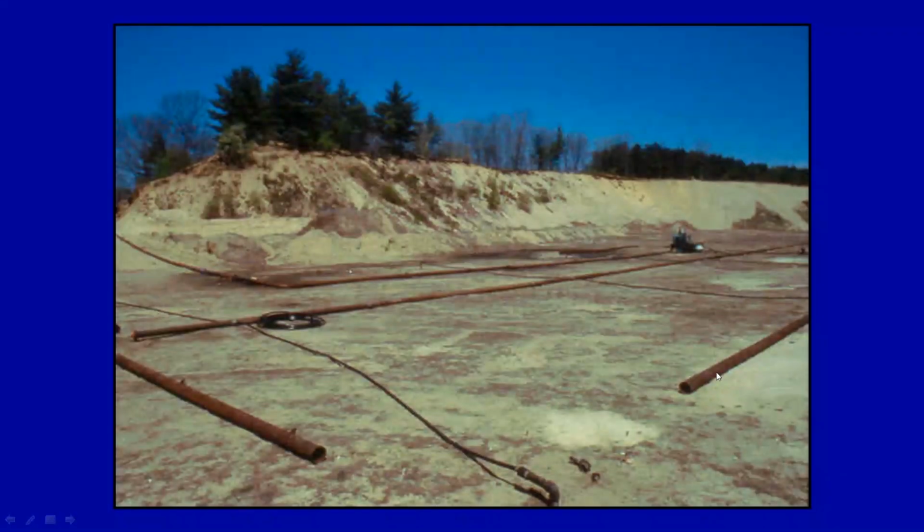Here we have an example of a shallow aquifer. This is going to be a tubular well field, 50 feet on center. A series of small diameter wells are manifolded. This is the pumping test, and to a suction manifold, to a suction pump, and the discharge is being run up and out of the particular basin. So shallow aquifers certainly are still potential high yielding sites.